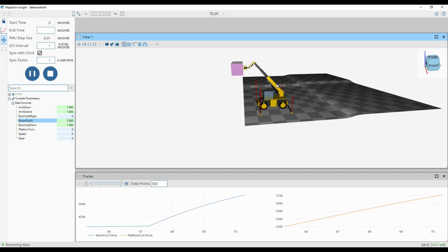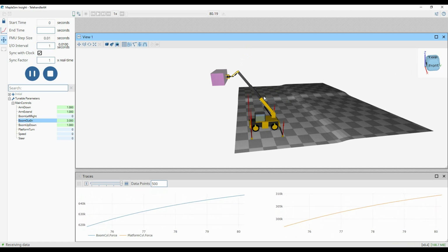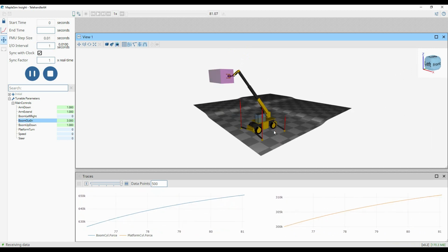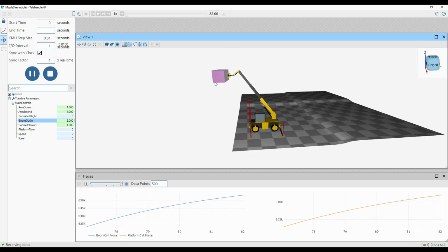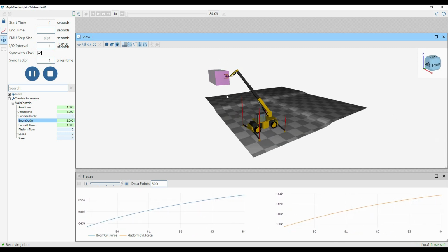And you can see the boom extending. Again, everything is dynamic here. This is only the 3D view, but you can imagine that whenever I change a value here, that hydraulic circuit is providing the power and force for this cylinder or that extension for the boom to happen. You can see how that changes the forces here. And IK is in place to keep this platform leveled as well.